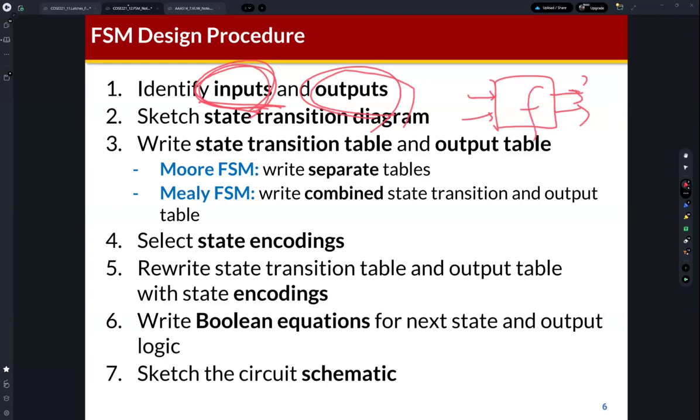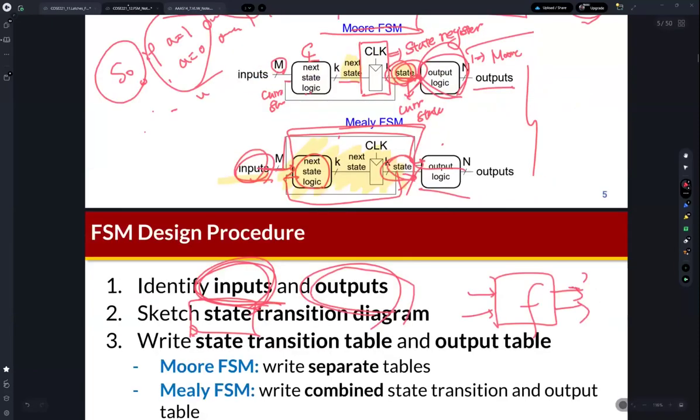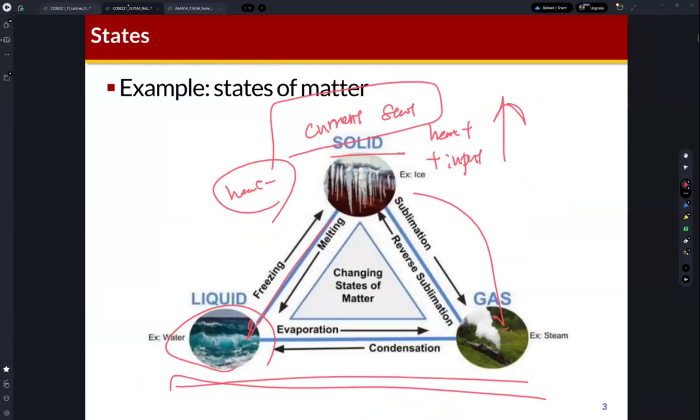Firstly, we need to define inputs and outputs, and we need to define the functional specification, right? The functional specification is that based on the input, outputs are generated. So this is the FSM design, which means that we also need to define states. If we design an FSM, then states will be changed by input signals.